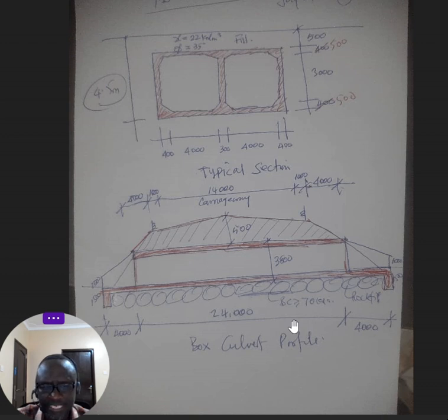It means it can be sustained at a point where the bearing capacity is at least 50 to 75. So if you excavate and you have done your DCP testing and the rest, and you know that at maybe 1.5 meters or 2 meters you have hit soil with bearing capacity exceeding 50, it means your rock filling can start from there.